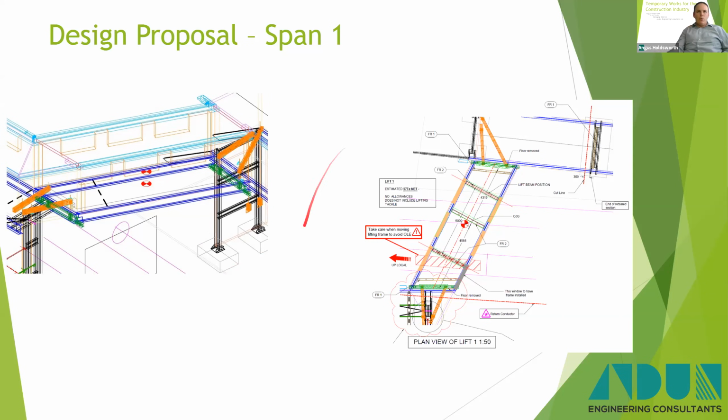So what we did, we used the self-weight of the structure that goes down these piers here, and almost like a seesaw arrangement here to support this span here, which is going to be cut out, and the same on the other side. So we got a beam that went under each end there in green, and then that's picked up by a pair of super slims there and a pair of super slims there that take it back and down the structure and restrain it, so we could cut the whole thing free, and it would sit there on those temporary supports until we lifted it out with the crane.